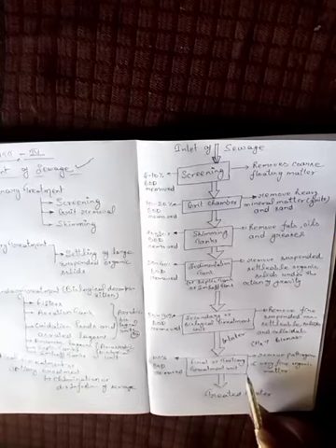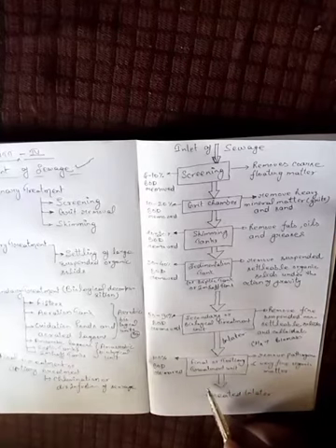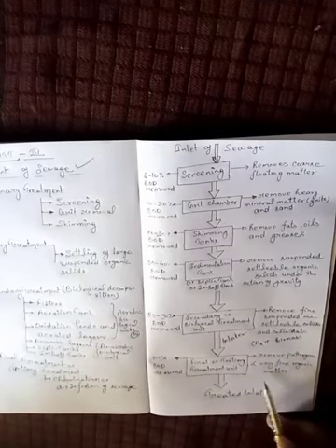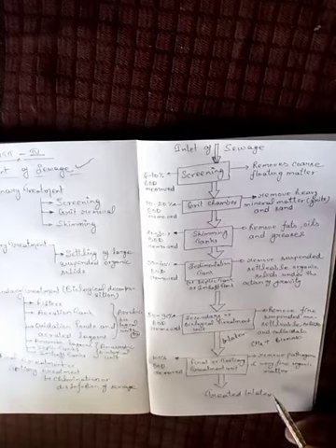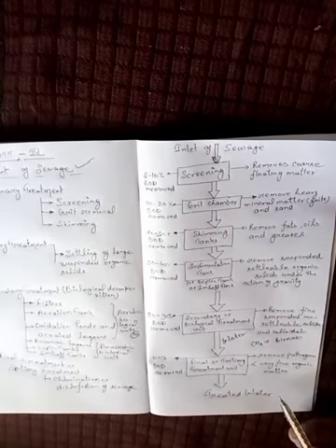The last step is the final treatment unit. In this process, pathogens or bacteria are removed by various chemical actions such as chlorination, disinfection, or the utilization of alums, bleaching powder, etc. In this step, 100% of the BOD is removed from the sewage.